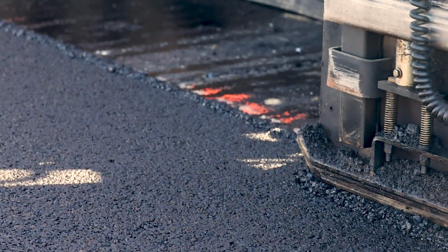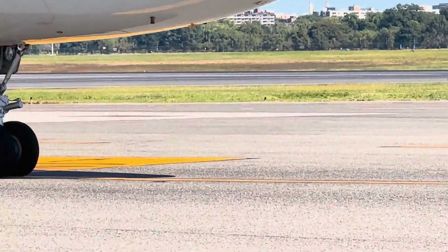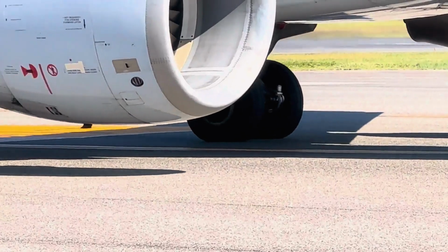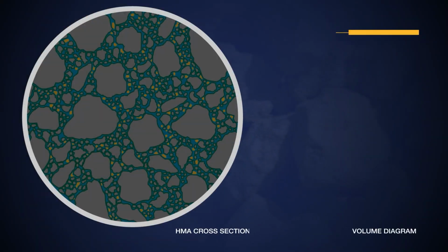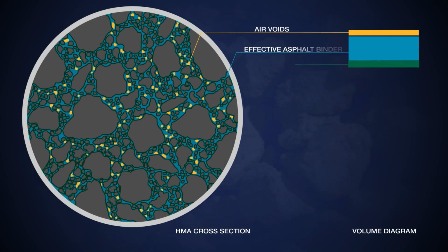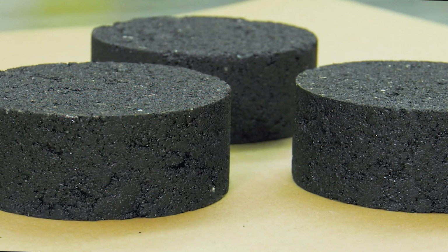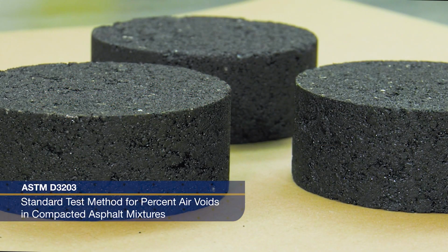Asphalt mixes require air voids to allow additional compaction under traffic and a slight amount of asphalt expansion due to temperature increases. Air voids are the small air spaces between coated aggregate particles. In a mix design, this is represented as percent air voids. The FAA specifies 3.5% laboratory air voids as a design target when developing a job mix formula.